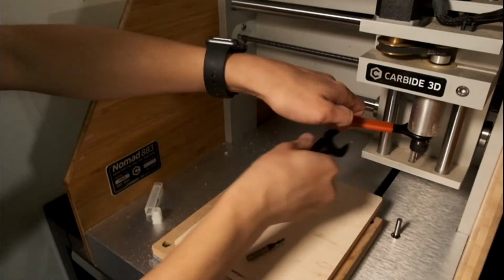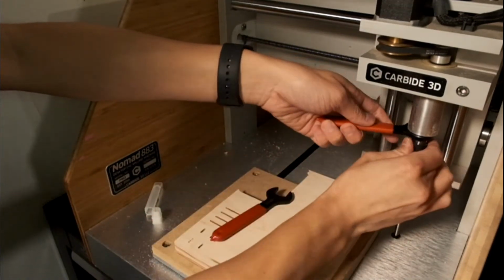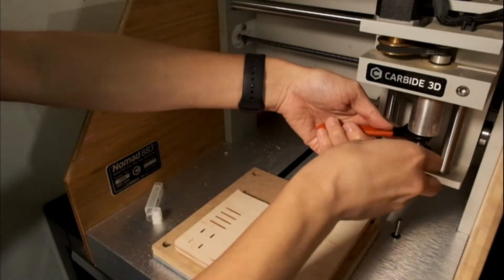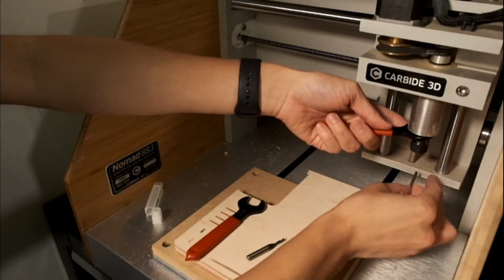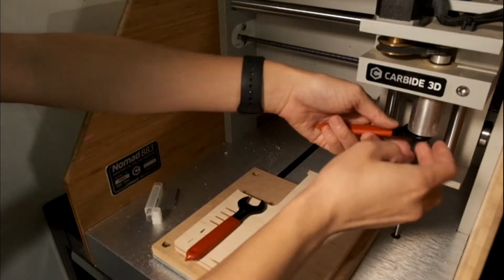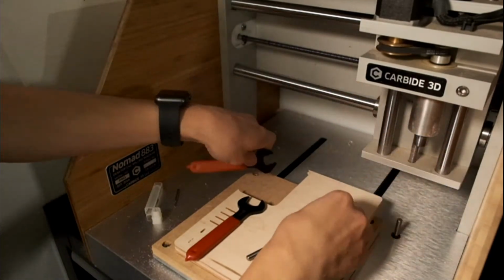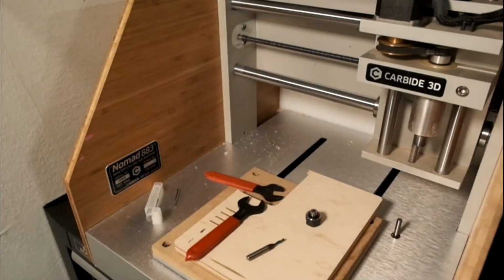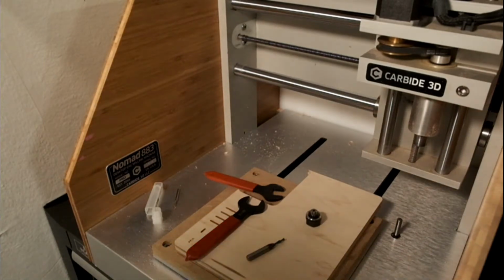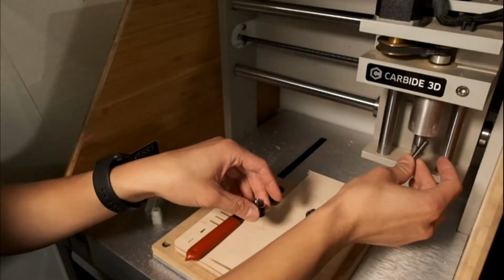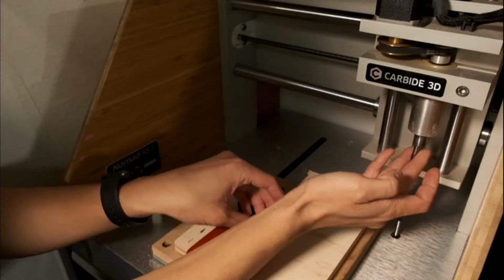Now people are going to complain immediately that I need to choke up on the tool more than it appears because, silly me, I need a 1/4" collet. These longer end mills are meant for full-on routers, so you can only shove this into the spindle so far before it bottoms out.